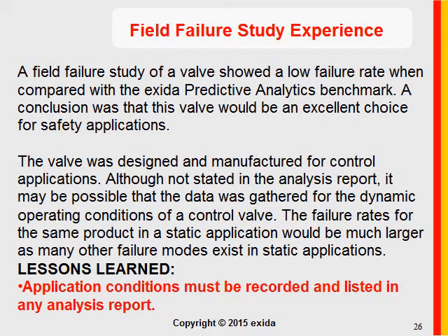Let me go on. However, the predicted lambdas with FMEDAs also come from manufacturers' data. Absolutely not. Nothing done by Exida is based on manufacturers' data. I will readily admit that other certification bodies and other people doing FMEDAs do use manufacturer's warranty data, which, as I said, is typically quite optimistic.